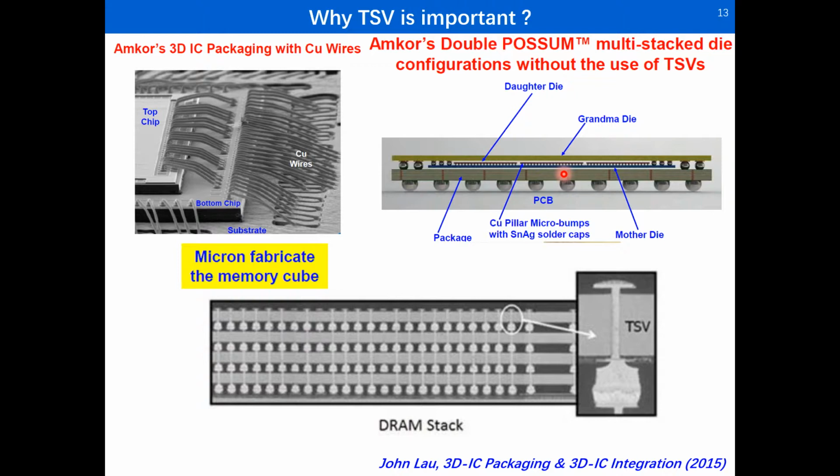Both of these above two methods have shortcomings. First, the sizes of the dies must increase gradually, a smaller one to a larger one, and then an even larger one. The second problem is only the edges of the die are used for input-output interconnects, and the central part is not used. Then we can note the benefits of TSV. The sizes of the die can be very uniform, and the I/O bumps can be everywhere on the die, even in the central part. That increases the I/O density.